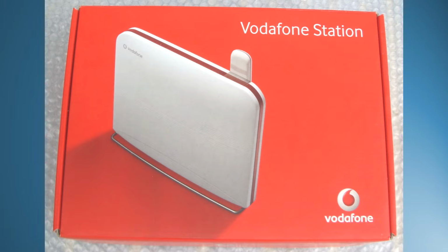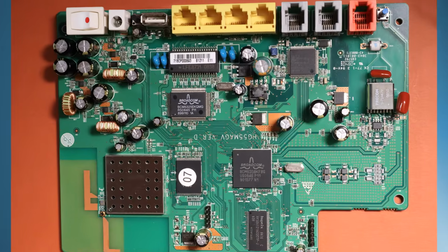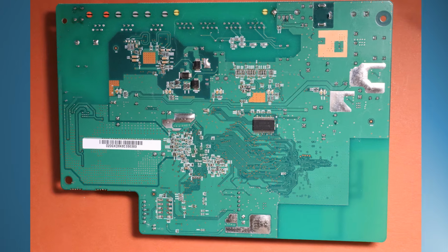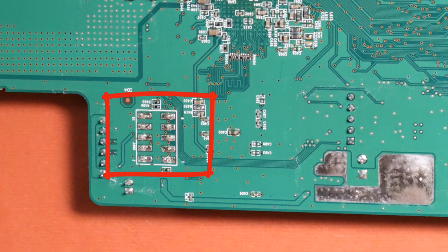To show how to find the JTAG pinout using a multimeter, we use another router's board that I have hacked in the past. In this case, it is an old Huawei router, an HG553 distributed in Italy by Vodafone. If we look at the board, we can see that the system on a chip is a Broadcom MIPS chip, and that the possible header candidates are on the other side of the board and are these pads, 10 pins arranged in a double row.